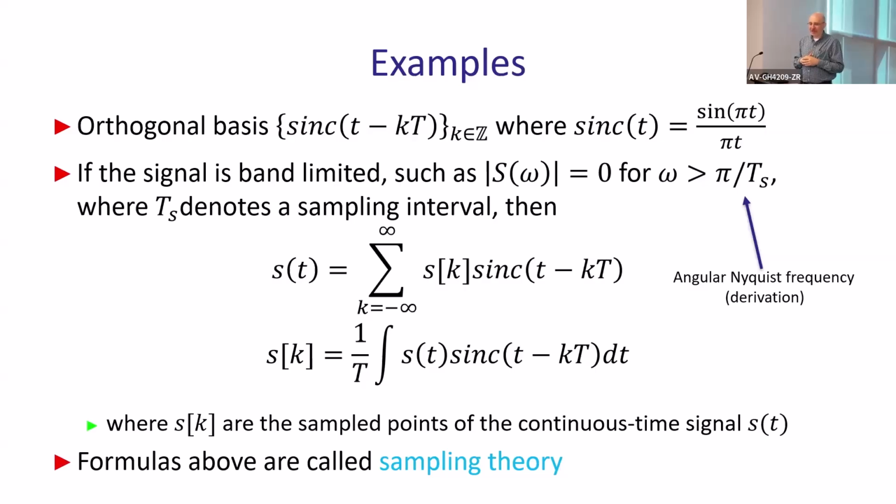That energy will be reflected onto other frequencies, which you don't want. So you will introduce additional artifacts by sampling itself. You need to be very careful to filter first with a low pass filter, remove all of the higher frequencies above Nyquist, and only then sample. So this is how it works. Any questions?